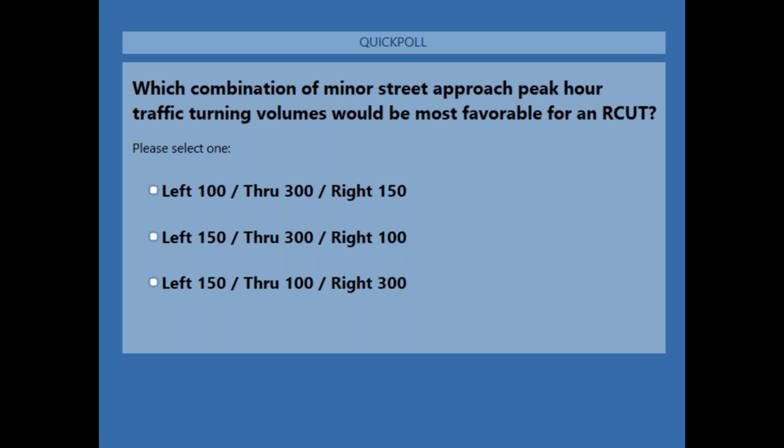And we do have a question in the questions box. Do R-CUTs accommodate large farm vehicles safely and effectively? Great question, and a very significant issue. So what agencies have tried to do to accommodate slow moving or oversized farm equipment is to basically extend the U-turn lane, the bay or the U-turn lane, all the way back to the main intersection.